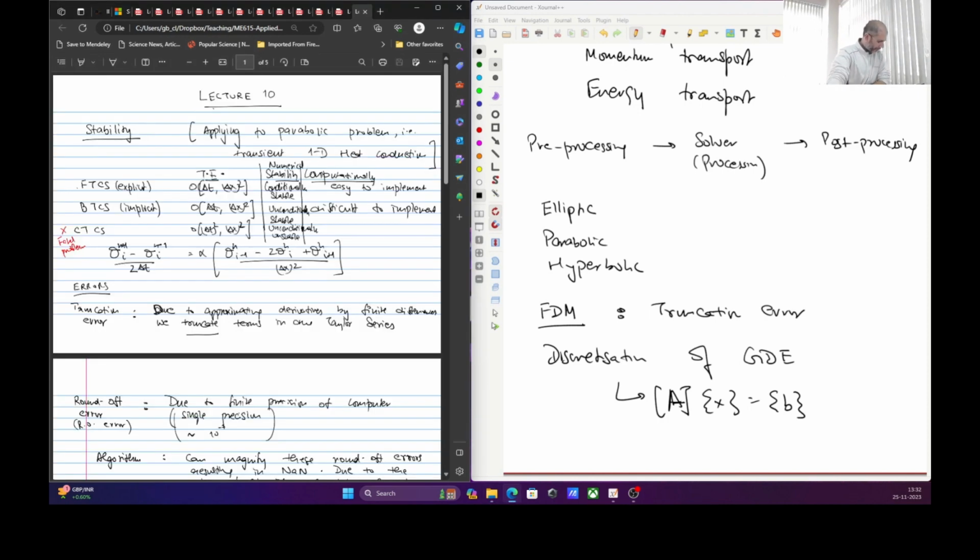Lecture number 10. So that's when we moved on to the problem of stability, or the issue of stability. So stability is where most of the issues come with explicit scheme, that there is some parameter that has to be constrained. In this case, it was a numerical Fourier number which has to be less than half, and that puts a condition on your time step or mesh size.